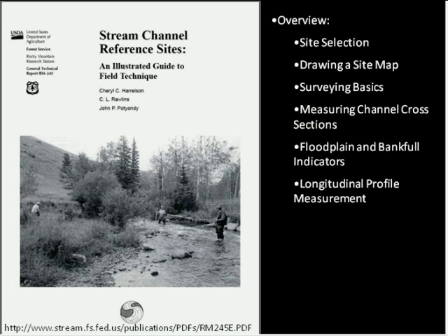Most inventory and assessment protocols require various field methods, and this guide covers the most common techniques, including basic topographic surveying, measuring channel cross-sections, and longitudinal profile measurement. I highly recommend this guide because it's clear and concise, and it covers many of the field methods and techniques necessary to analyze and design stream crossings.